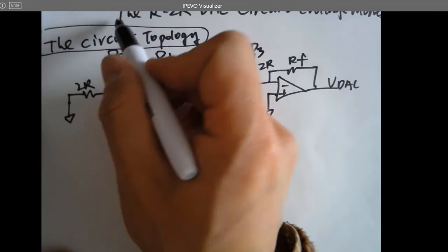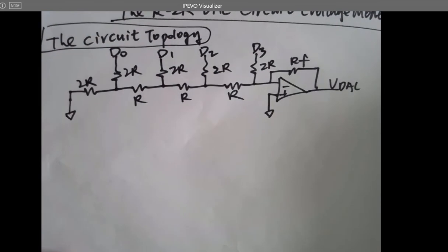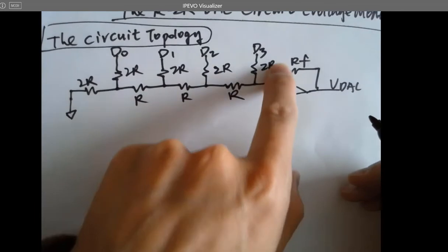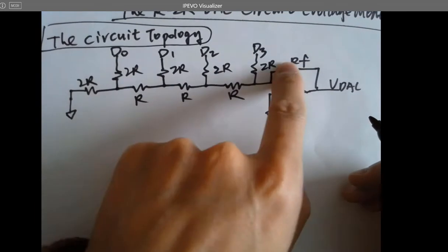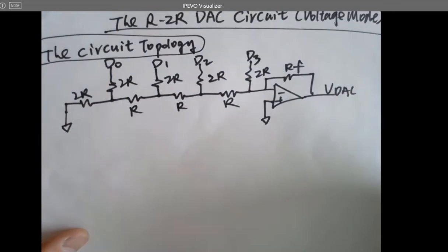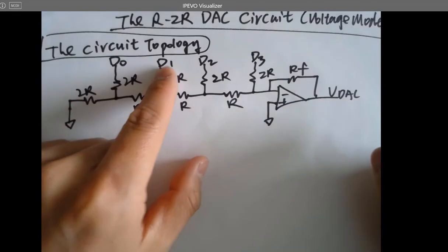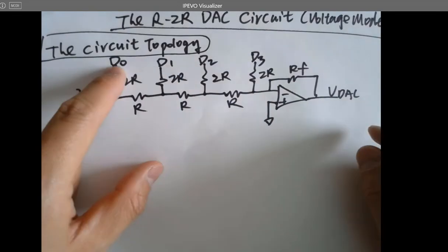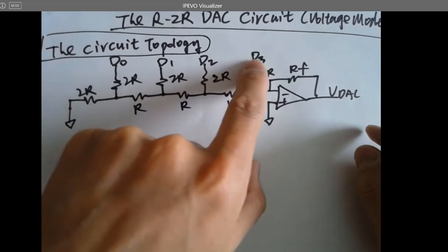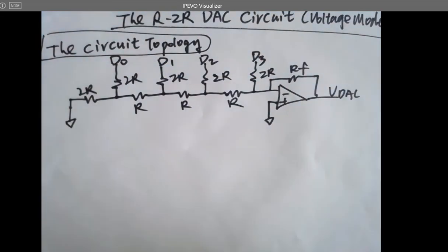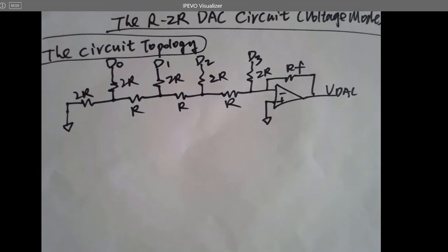How do you analyze this circuit? Why is this doing the job? So superposition actually needs to be applied to this circuit. Why? So these are the input signals, right? Input digital signals, 1 or 0. So if we use 5 volts as a VREF, then 1 represents 5 volts. 0 represents ground. So you are actually connecting a 5 volt battery or ground to these digits to make up a digital signal input, right? And you are supposed to get an analog signal output.